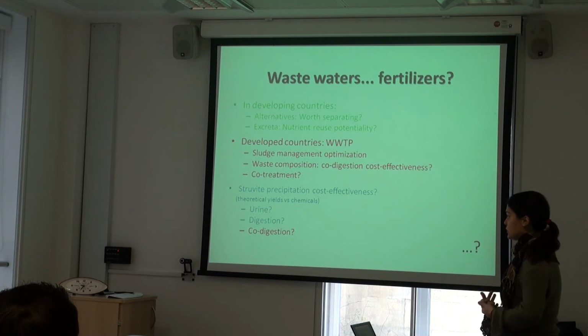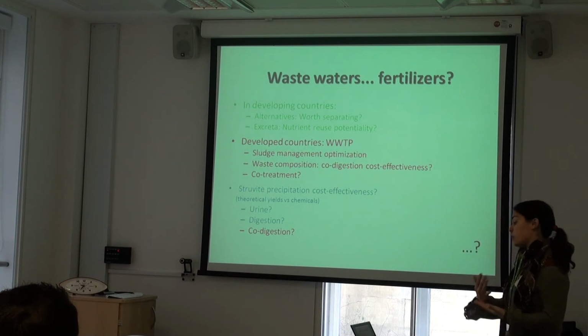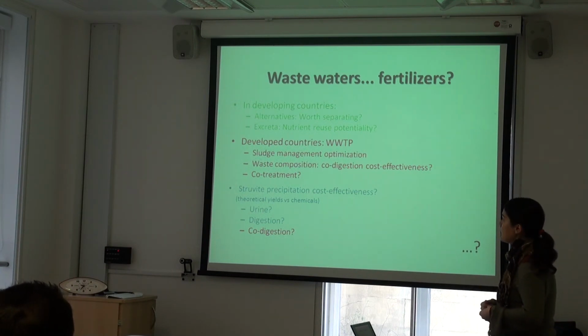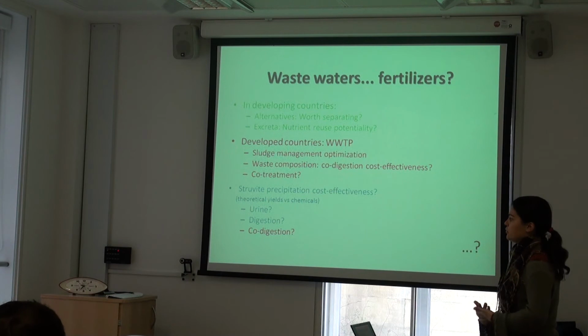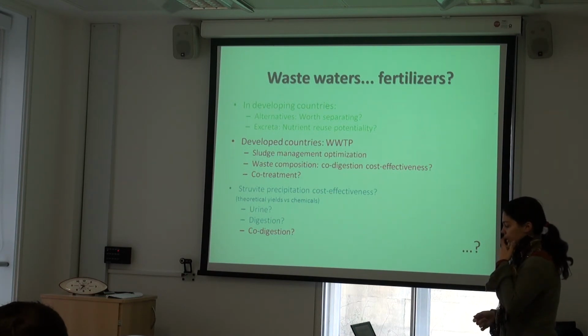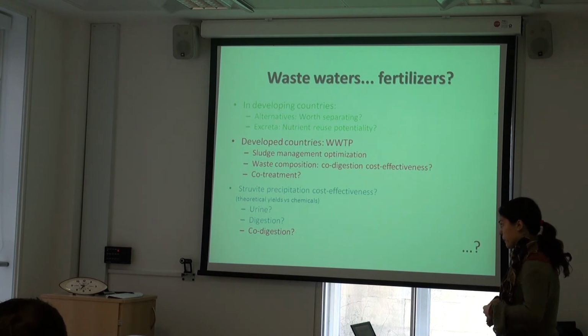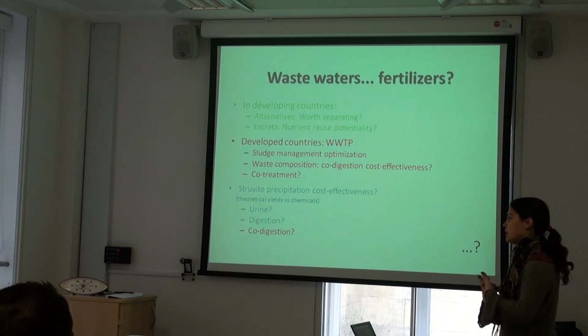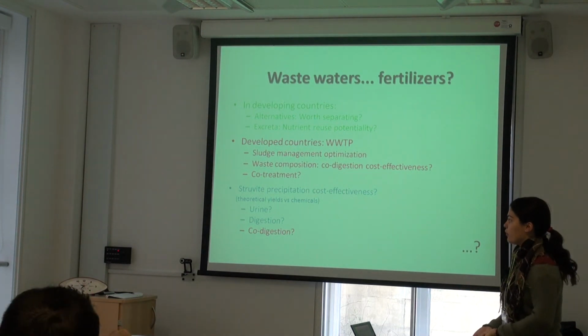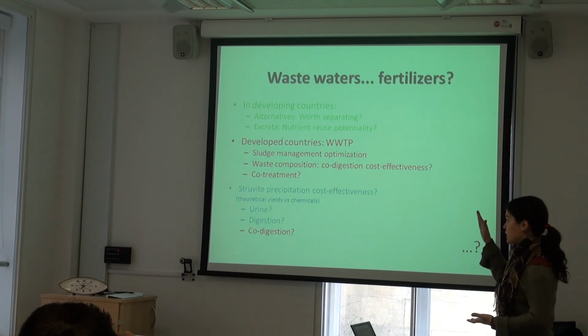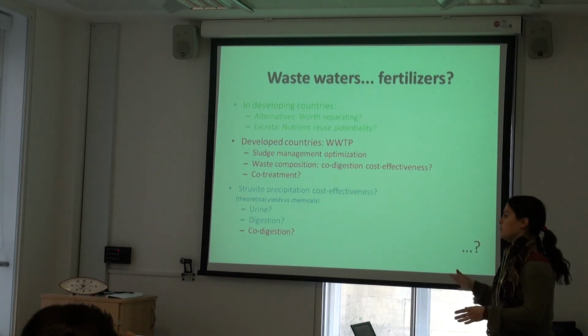And I consider that waste composition and co-digestion have a lot to do with this, in the sense of what would be the optimal way of doing that, what kind of compound you would like to mix in what quantity, and how effective this is. And further on, I asked myself, and I haven't seen anyone that has done it, and I don't really know why. All the literature refers to co-digestion, but really, in the secondary treatment, they have exactly the same problem, that the waste is very unbalanced, and the amount of nitrogen is very high compared to the amount of carbon.